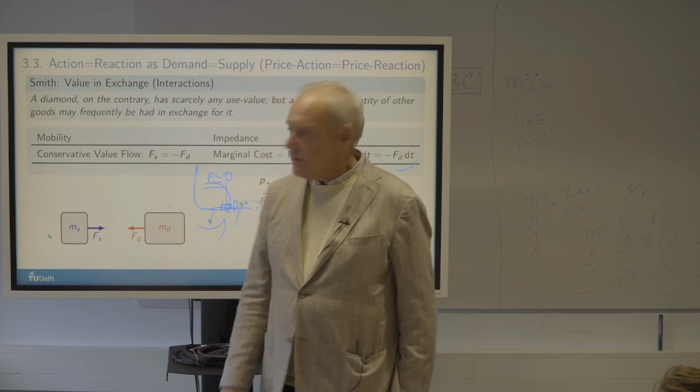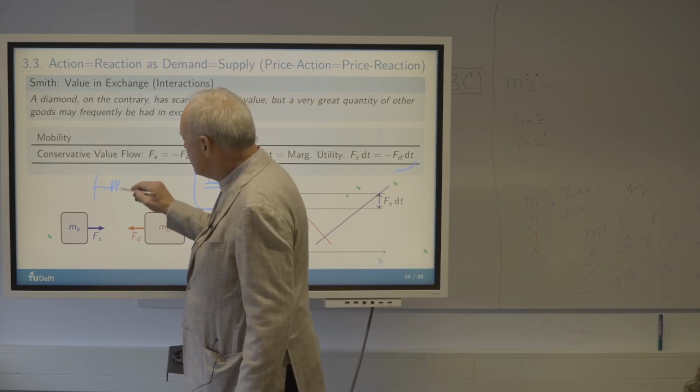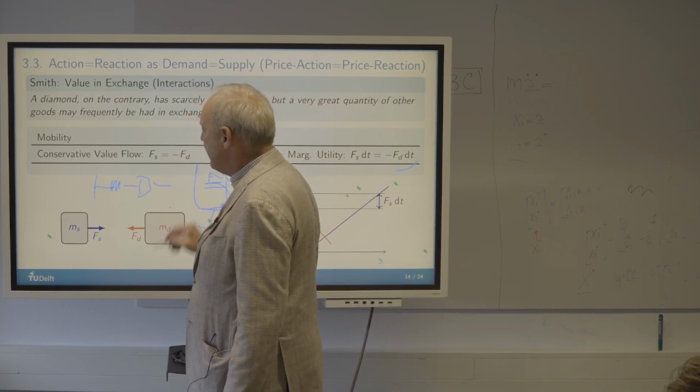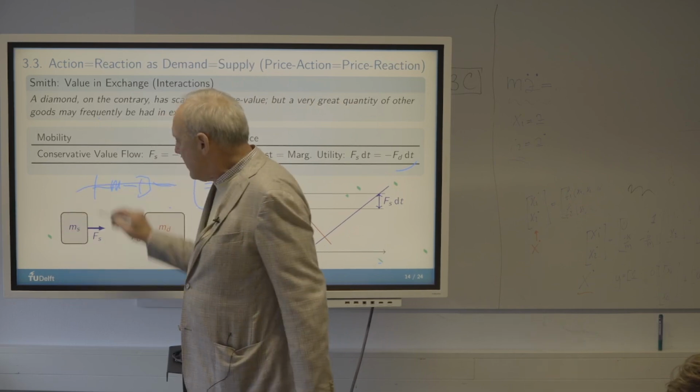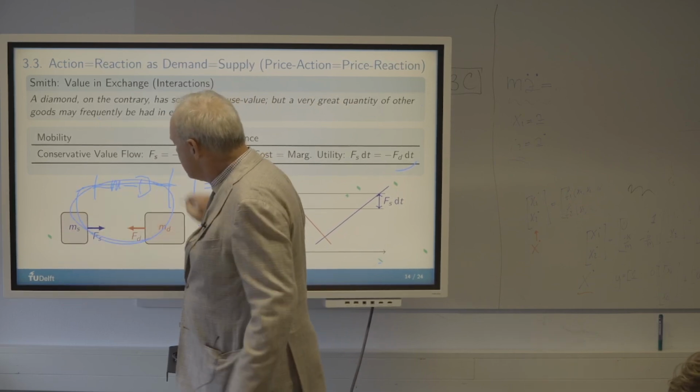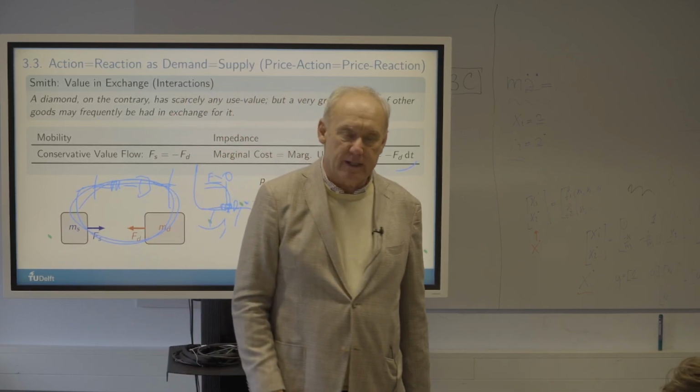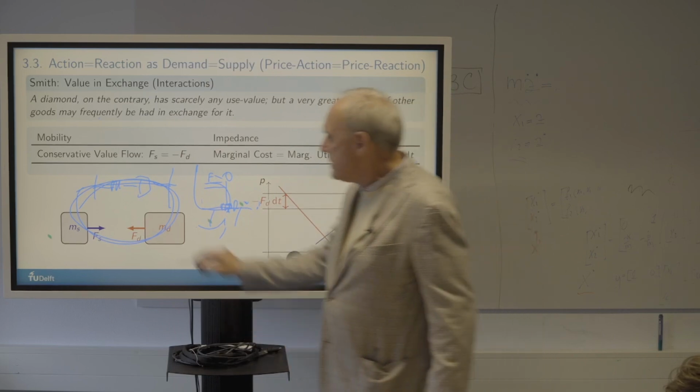So if there's a force going through a spring that's induced by a damper, then the flow of momentum goes like this, and here's another one, and it just circles around like that. Okay? Because these walls are connected.